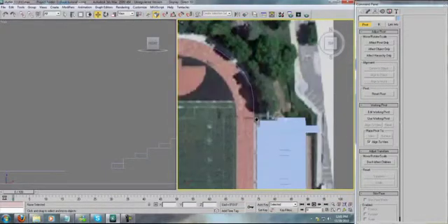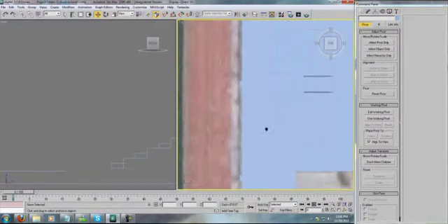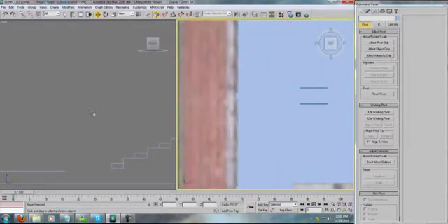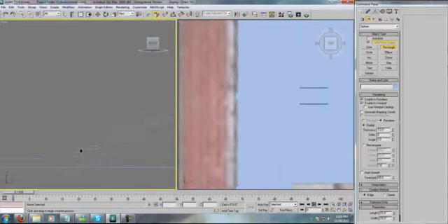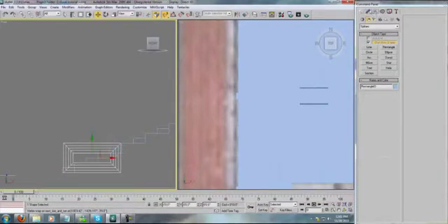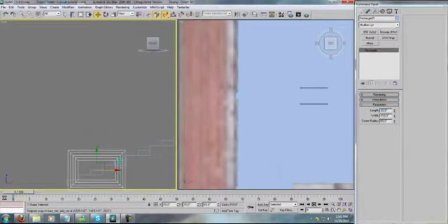If we were going to be modeling for something like that, typically you would see handrails in the middle of these aisles. That's not the case here, but I'm just going to build some for the sake of showing you how to do it. So let's go into our rectangle, snap to these center points, make sure our height is at 3 feet, and then snap it up.